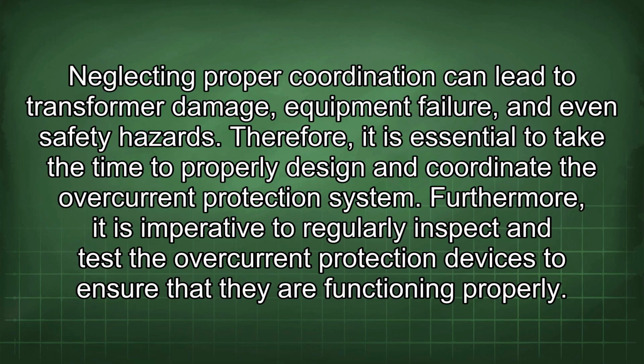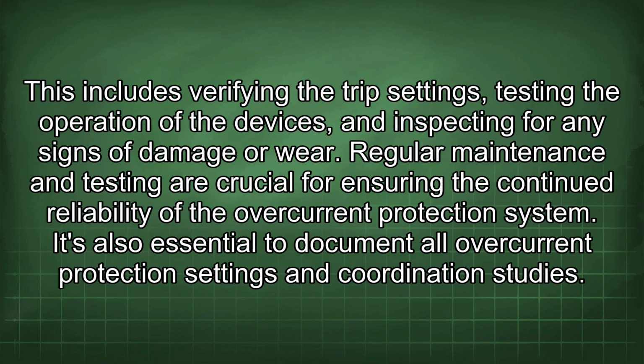Furthermore, it is imperative to regularly inspect and test the overcurrent protection devices to ensure that they are functioning properly. This includes verifying the trip settings, testing the operation of the devices, and inspecting for any signs of damage or wear. Regular maintenance and testing are crucial for ensuring the continued reliability of the overcurrent protection system.